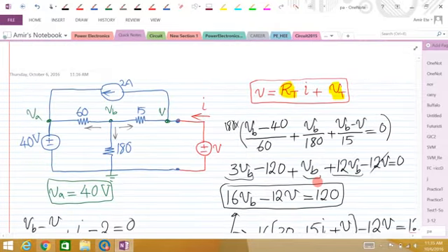So just to recap, in this video I tried to use this approach of finding a Thevenin of a circuit. We apply or attach this voltage source V, and just be careful about this voltage polarity and this current direction. Based on this circuit, we try to find the relationship between V and I, something like this. So it's a parametric equation.